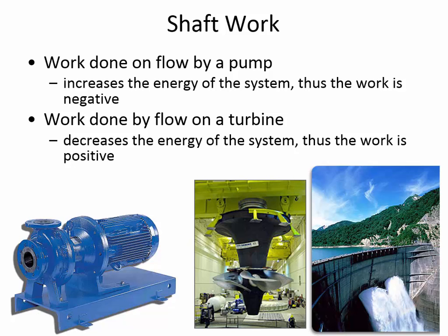If you add a pump to this, then the effect that you'd notice, what you could actually see when you turn on that pump, is that all of a sudden the water is spraying out with a really high velocity. And so you might draw the incorrect conclusion that what the pump is doing is actually increasing the velocity of the water. That's the direct effect that it has. But actually that's not the direct effect, that's the indirect effect.